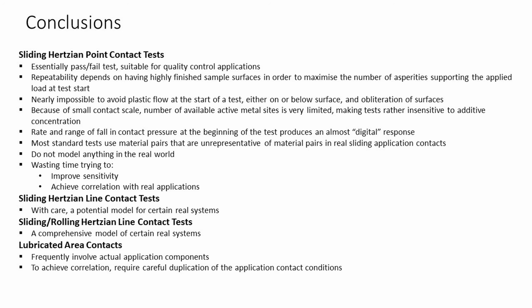Of course, most standard tests use material pairs that are unrepresentative of material pairs in real sliding application contacts. And, of course, sliding Hertzian point contacts do not model anything in the real world. It's a matter of opinion, of course, but I reckon it's pretty much a waste of time trying to improve the sensitivity of sliding Hertzian point contact tests, or indeed to try to achieve correlation with real-life applications.